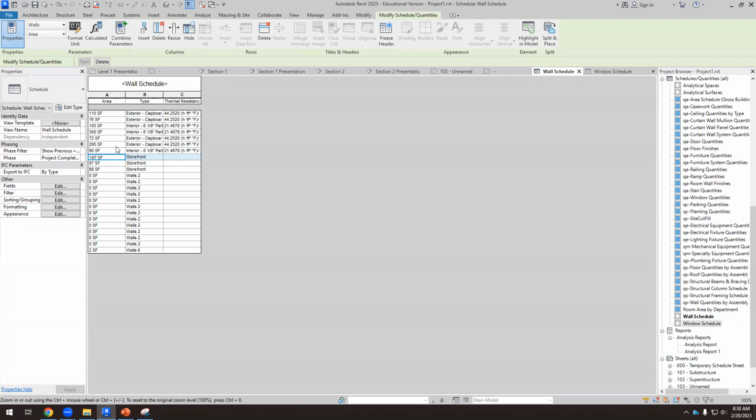And if we are analyzing the window to wall ratio, the windows are here, and the walls are in the denominator. So the wall area is this. We have to add up all these numbers, and then the window area is all the curtain walls.